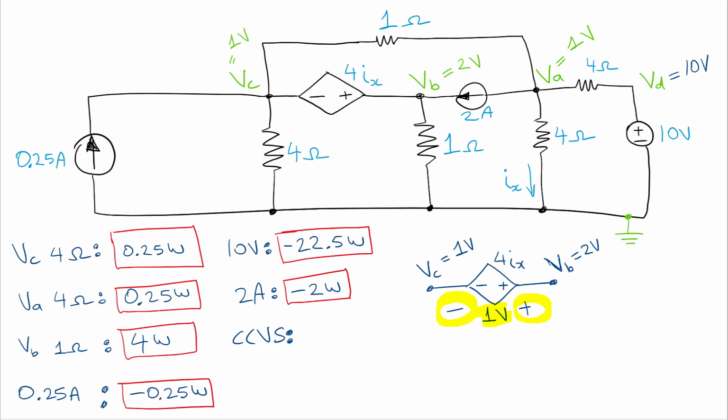So we're going to examine the circuit, and then let us look at the right side of the circuit where we know we have 2 amps going in. So we have 2 amps going in, that's 2 amps, and if we found out what's the current through this 1 ohm resistor, then we can use Kirchhoff's law to find the current flowing into that voltage source.